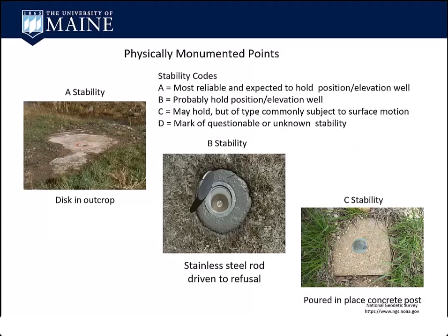So these are different kinds of physically monumented points. There's a disc in an outcrop of ledge, stainless steel rod driven to refusal. A bunch of companies make them. Berntsen makes them, and it's very stable.